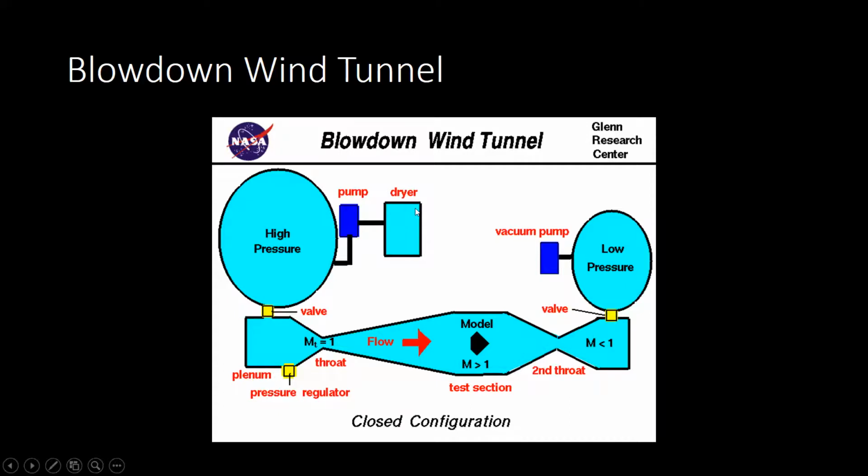This dryer also has multiple functions. It's not just to reach the stagnation temperature, although that is one of the primary concerns, but it can also help remove any potential moisture. Another thing I like to talk about is that as you expand this throat right here, the temperature drops very quickly. And that's one of the reactions of talking about supersonic flows.